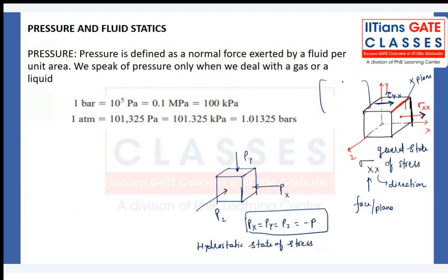No distortion will occur. There will be only volumetric changes, right? Only volumetric energy will be stored. Volumetric strain energy will be stored. There will not be any distortion energy in this case.